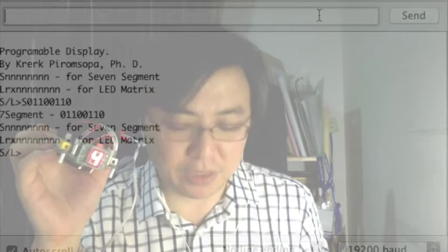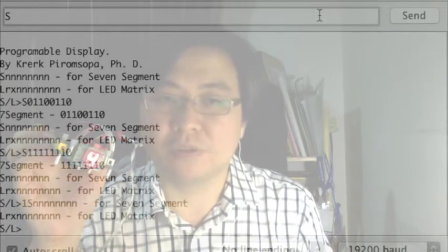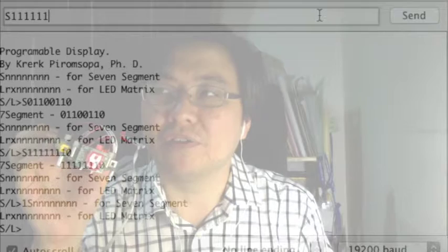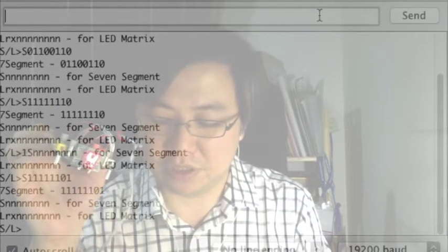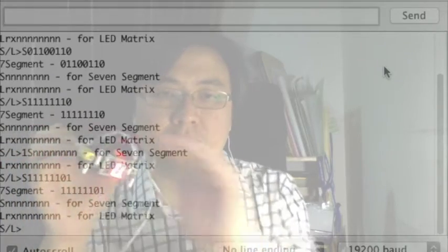Alright, and let's say I want number 0. So you just draw the bitmap of number 0 in your mind. You would see that it's on for most of the bits. Now you got the idea. I can reprogram the 7-segment to be whatever number I want. Just type S followed by the bit patterns.